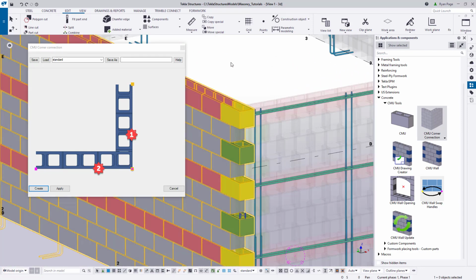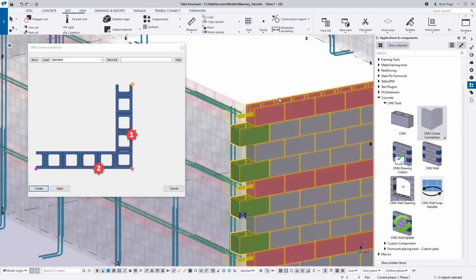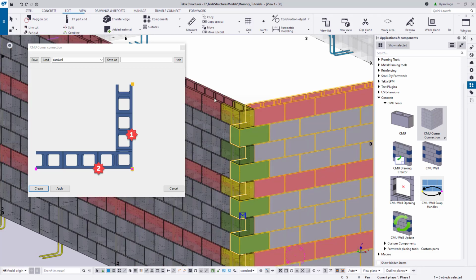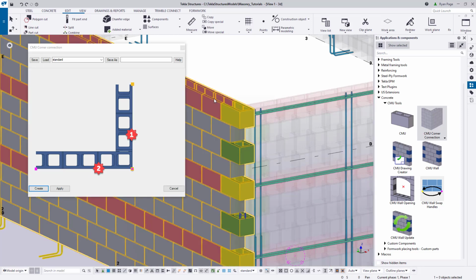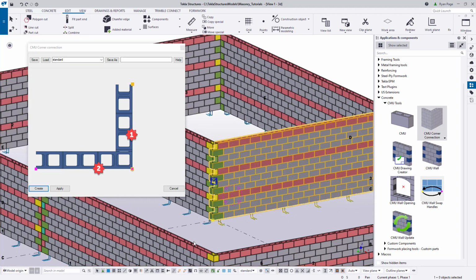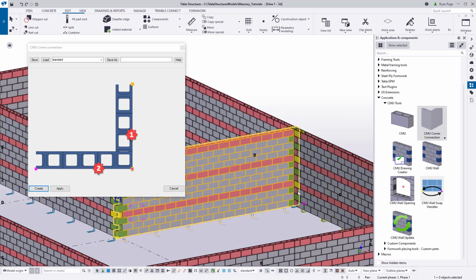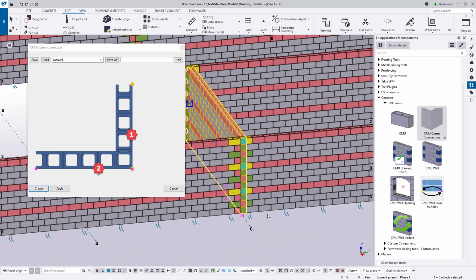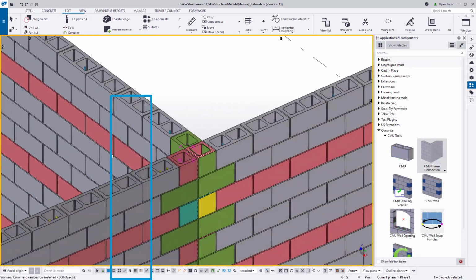But you can see what the tool has done is it's gone ahead and adjusted for the walls, the end conditions, as well as the course configuration so that they interlock. Now that we've taken care of the corner, we can go to the wall along 3 line and remove the end conditions off the start of the second withe so that the perpendicular walls fit together.